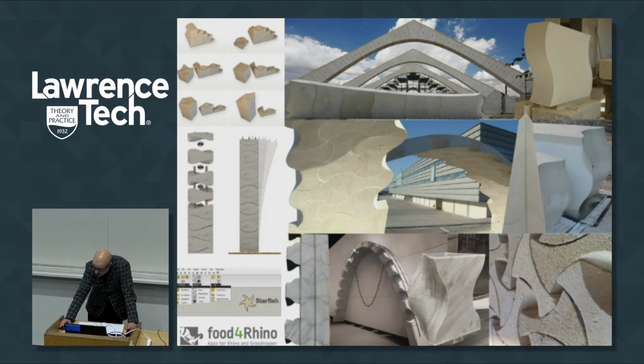designing subdivision ashlar of the vault both as ornamental, so aesthetic, and structural behavior, varying the shape of the vault system in a particular parametric way, automatically obtaining all the geometric data both for the manual and electronic cutting, CAD, CAM, CNC, of each individual block, automatically providing all the numerical data aimed at the structural analysis, and rationalizing the number of standard ashlar for the construction of many complex vaulted structures.